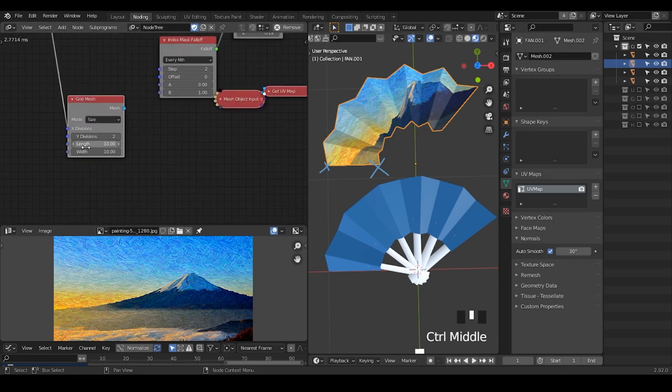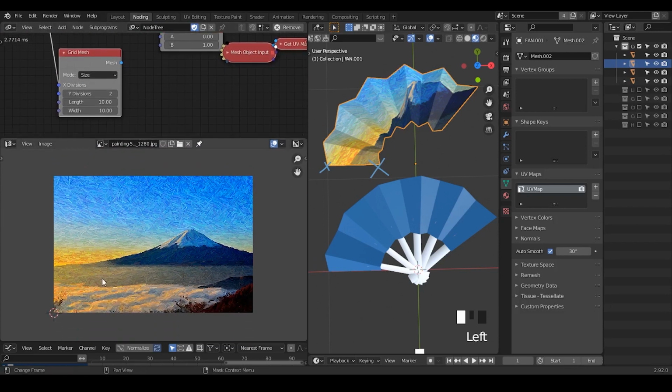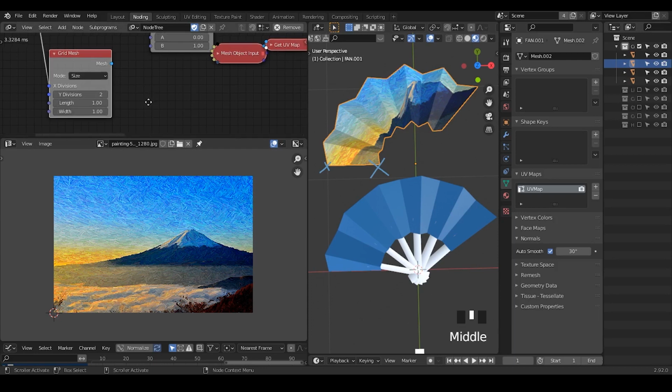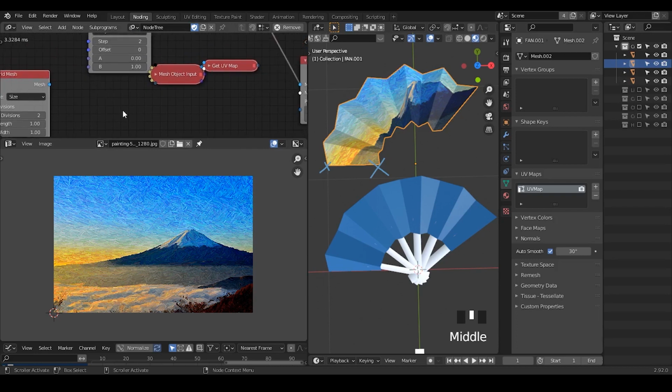So once we have all these things, we need to know a little bit of common knowledge about shaders. Basically, the shader UV map always ranges from 0 to 1 by default. So it does not really matter which size, which dimension, or which ratio of length over width your image texture has. The UV map always ranges from 0 to 1. So at least set that to 1 by 1 and we will see the effects very soon.